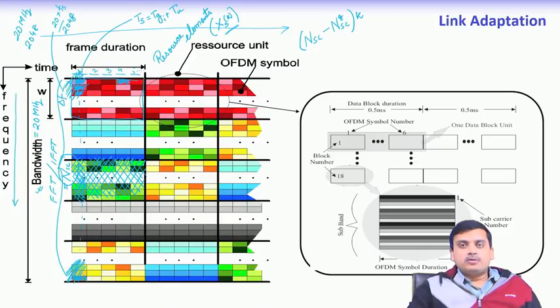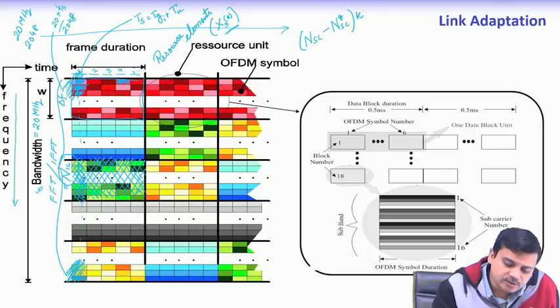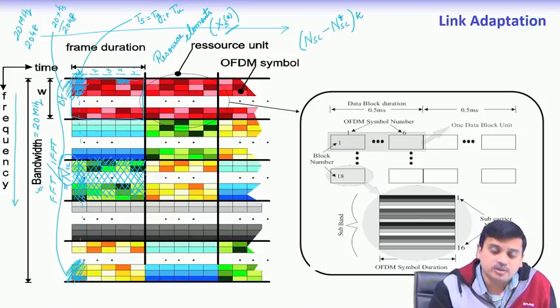Now, one should also remember that there is a forward error correction code. So, one has to have a certain larger number of bits to allow the error correction code, and one can choose different modulation techniques, and also one has to allocate these resources to different users. So, there is a certain minimum size of this block that includes a certain number of subcarriers and a certain number of time domain signals to form a resource block.